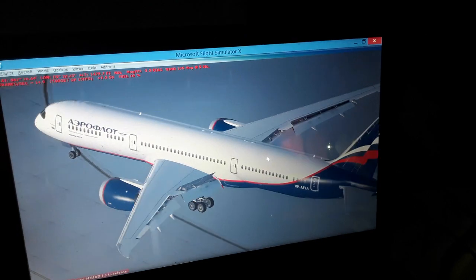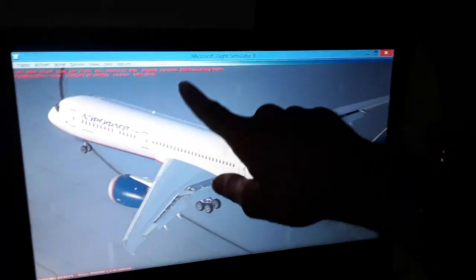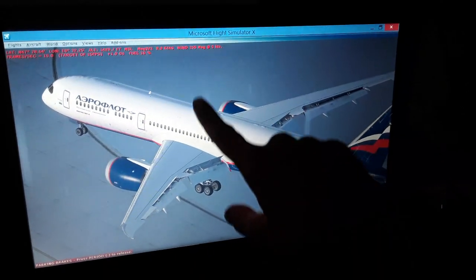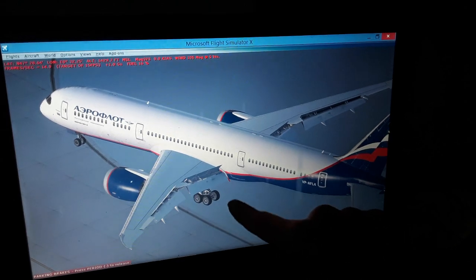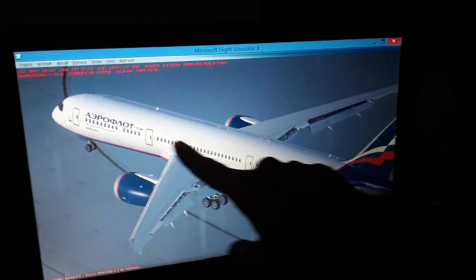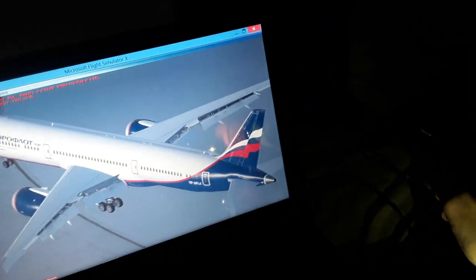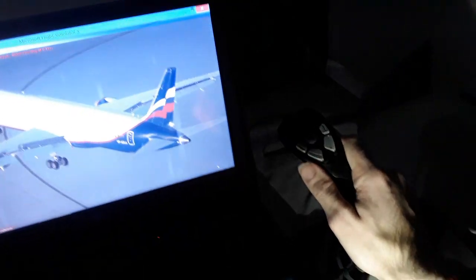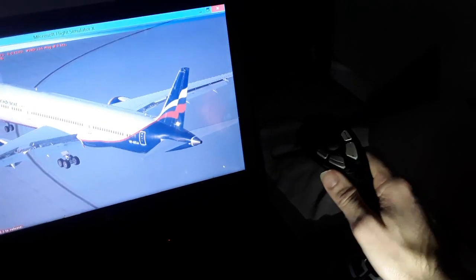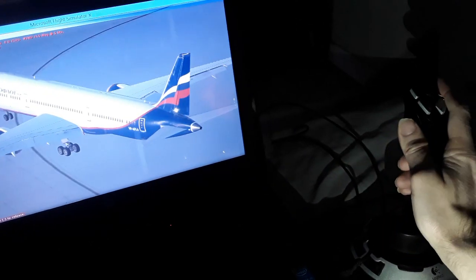We have also over here the lateral axis from wingtip to wingtip. We have the vertical axis through the center of gravity, which is pretty much close to where the mean aerodynamic chord is, the MAC. We have the longitudinal axis over here that traverses through the horizontal tail. So the axis through the horizontal tail over here is for making turns to left and right using the ailerons and the spoilers around the longitudinal axis using the flight controls here. Flight control using the side stick. You can see we make turns over here.